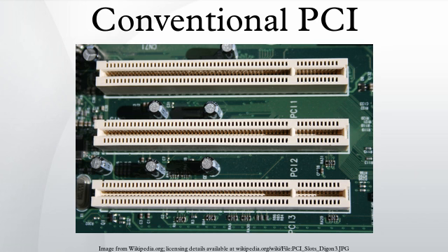The cycle after the target asserts TRDY, the final data transfer is complete, both sides deassert their respective RDY signals, and the bus is idle again. The master may not deassert frame before asserting IRDY, nor may it deassert frame while waiting, with IRDY asserted, for the target to assert TRDY.